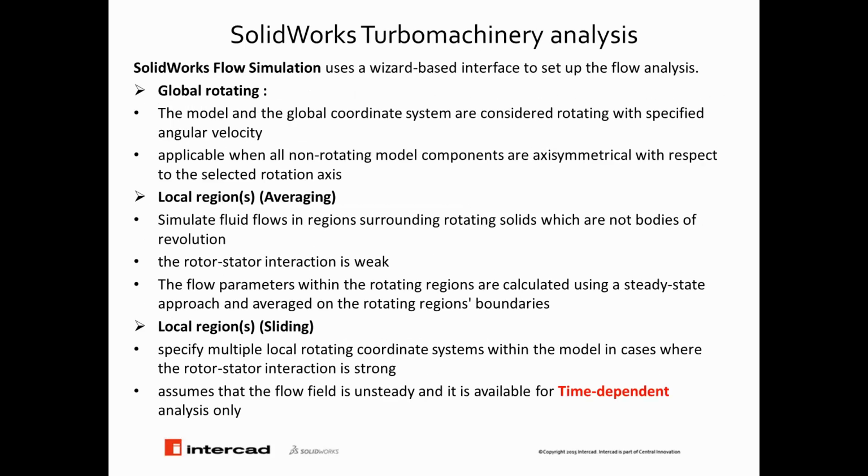As you know, SolidWorks Flow Simulation is a wizard-based interface to set up the flow analysis, and you can have three different methods to specify that there is a rotational region in your turbomachine and its interaction with the other regions. The first could be global rotating.